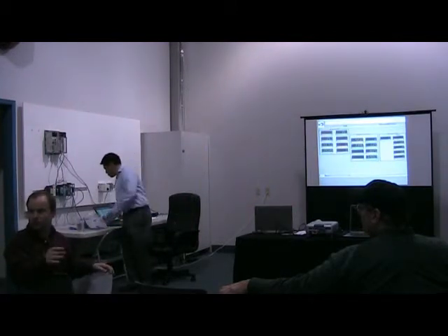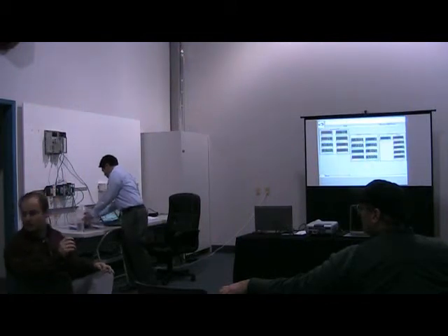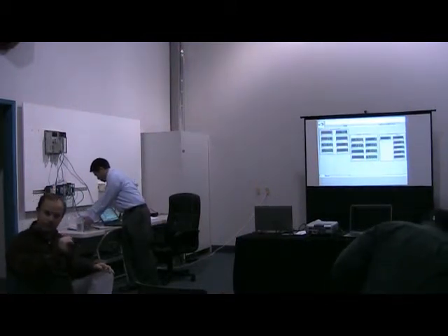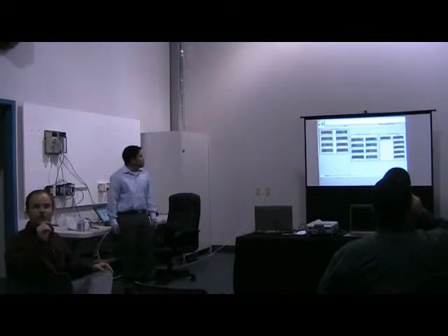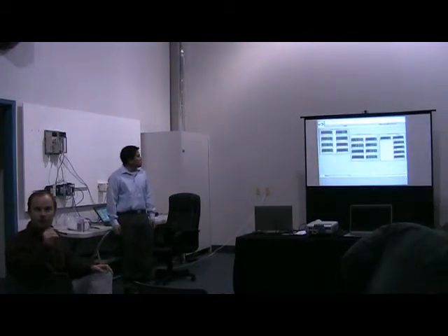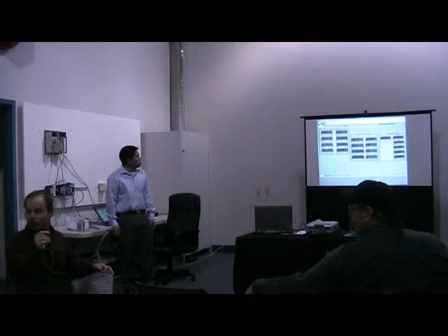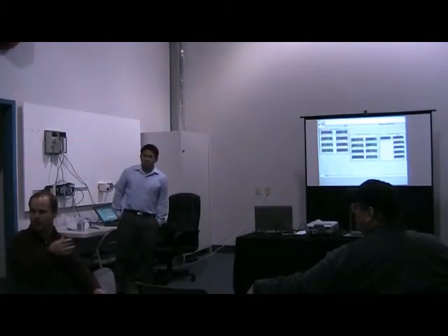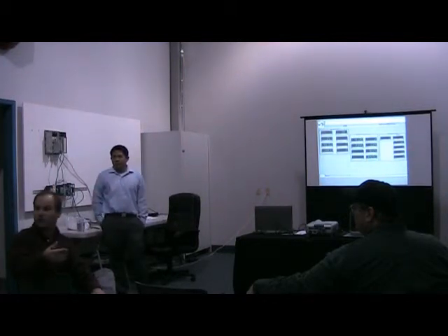It's just powering the instruments. It's basically a bus. If you lose the bus or a module dies, and your response time plummets for every node you add to it, there's a lot of negatives. I see minimal benefits versus the negatives of going multi-drop.